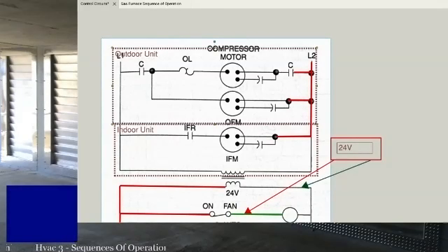So if you've got a single phase 240 volt appliance, it is perfectly fine, just like any other 120 volt appliance, to keep L2 on there at all times ready to go. And a lot of times it's set up like that. L2 is powered at all times, and then L1 is the only thing that gets shut off by an individual relay. But you'll see a lot of units where it cuts off both phases.